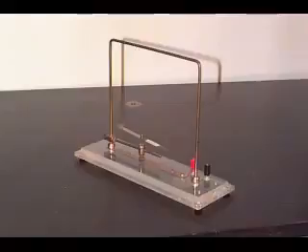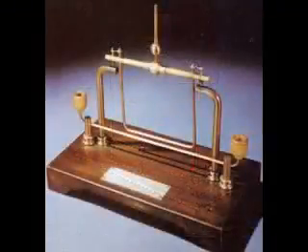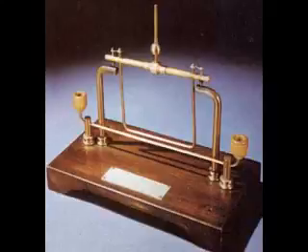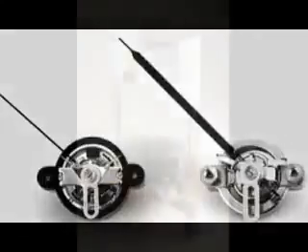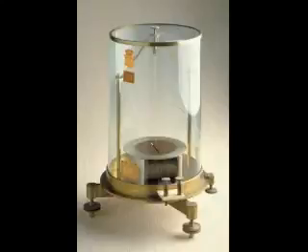If the magnetic field formed by the conductor is allowed to interact with another magnetic field, a physical force will be generated between the two sources of fields. If one of these sources is free to move with respect to the other, it will do so as the current is conducted through the wire, the motion, usually against the resistance of a spring, being proportional to the strength of the current. The first meter movements built were known as galvanometers, and usually were designed with maximum sensitivity in mind.